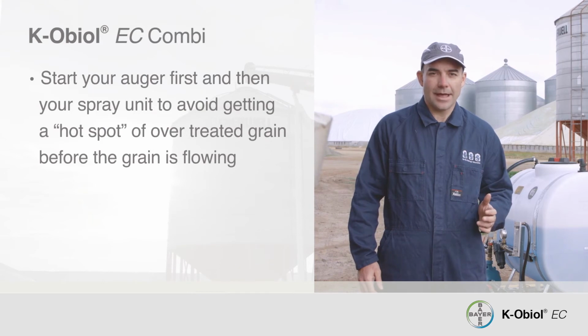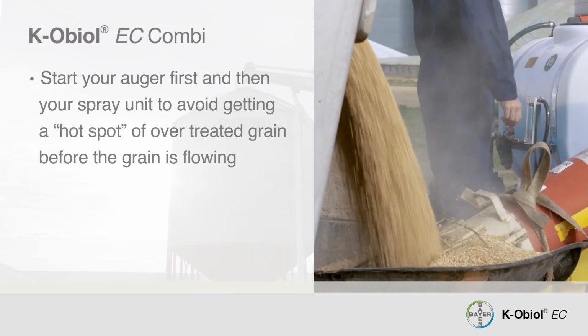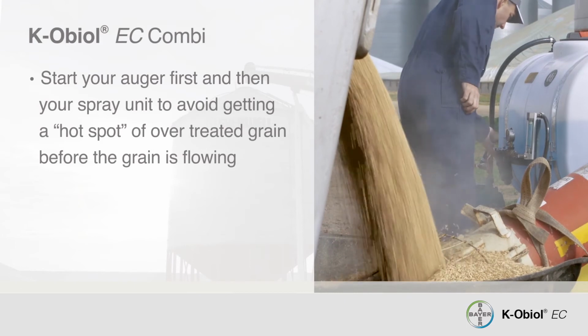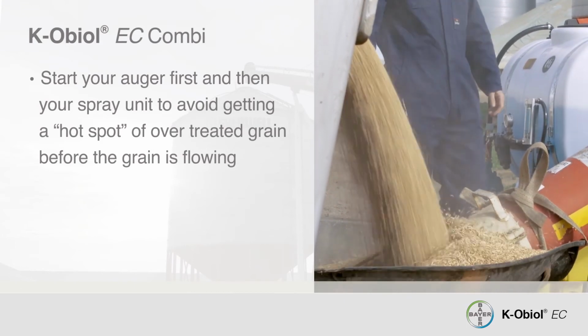Finally, start treating your grain. First, start your auger and then your spray pump. We recommend doing it in this order so that you don't end up with a hot spot of over-treated grain before the grain is flowing.